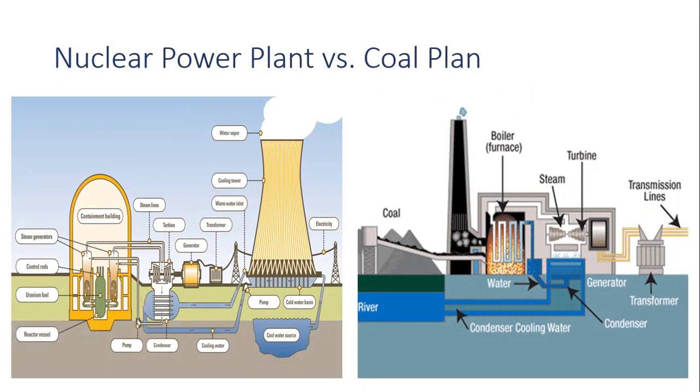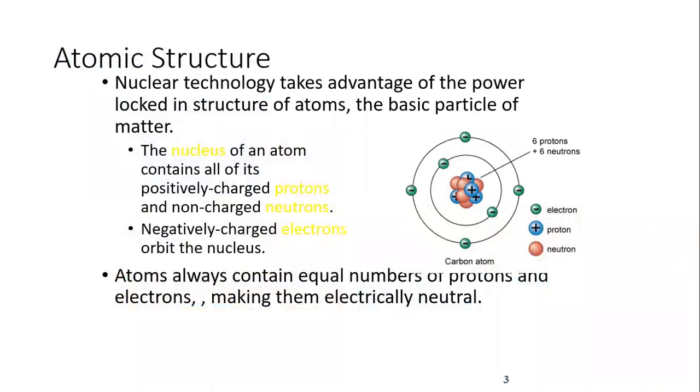The output control is extremely flexible. There are large deposits of nuclear fuels available. The coal-fired steam power plants need 1,000 tons of coal per day, therefore the transportation of that coal is also very high, and the cost of transportation is also very high. This is the major advantage when comparing nuclear power plants to thermal power plants, the coal power plants.